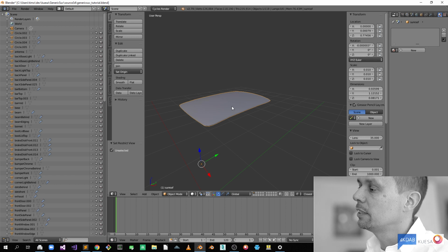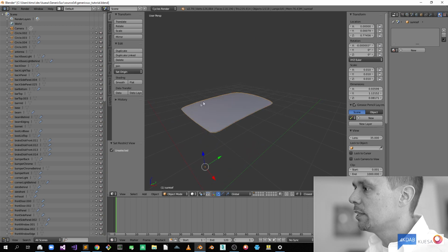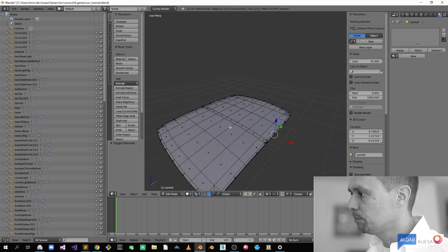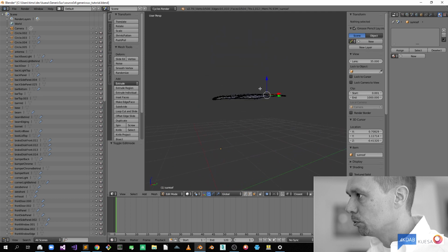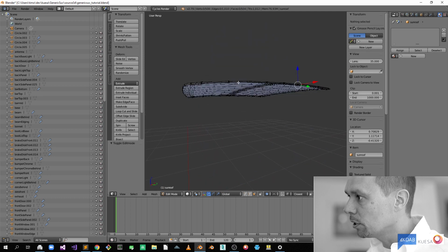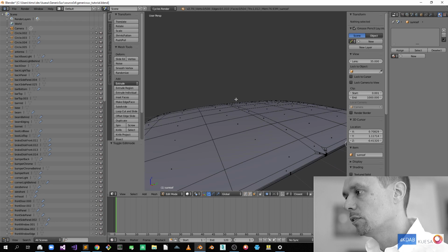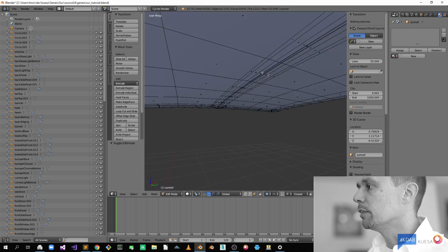But for this tutorial, let's pretend we are going to create an app for a desktop PC. So let's see. Currently the sunroof has about 500 faces. It's two-sided, so it's a closed volume, so to speak. But in my application, I want to view the car just from outside, so I'm going to delete all the inner faces here.